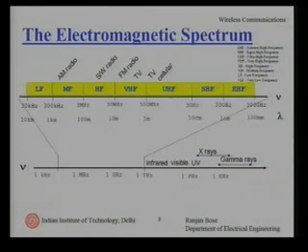Then there is another factor, which is rain, dust, fog. The higher the frequency, smaller the wavelength. In fact, at 30 gigahertz we touch the millimeter wave. There is a whole range of communication products today which work in the millimeter range. Now, the millimeter wavelengths, the size of the wavelengths is of the size of a raindrop. Fine? They start interacting. There is a fog or rain or big dust particles. These rays would get greatly attenuated and hence result in smaller coverage areas. Right? So, on this yellow strip, it is important to know where we operate. Also, from the point of view is how far can you send the rays.